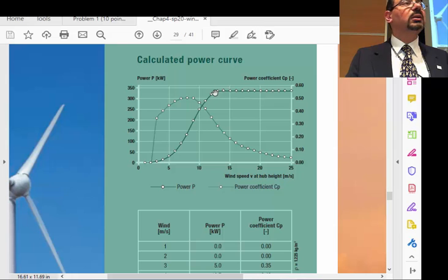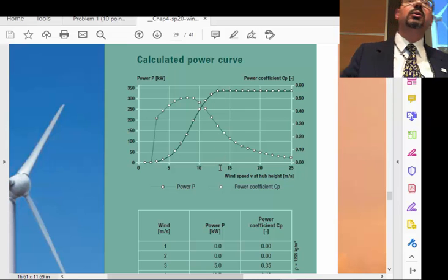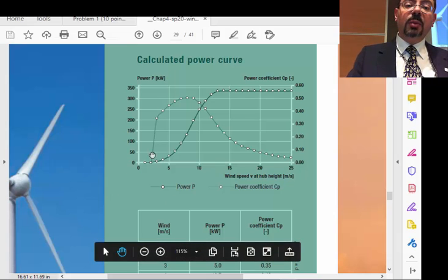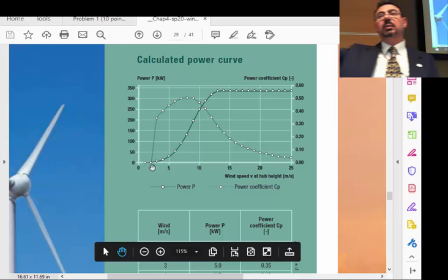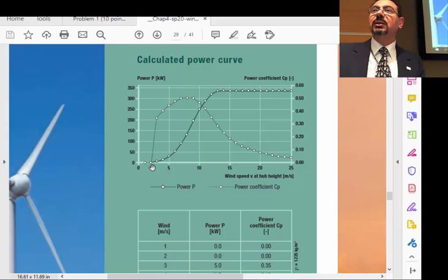Okay? So that he maintains what? He maintains the power cap. Okay? So this is the output curve, and this is basically the CP. When you hit the maximum power, the rated power, this would be the rated velocity, the rated speed. And the moment you start being online and people can put a load on your output, that is the cut-in speed, when you are allowed to produce power.